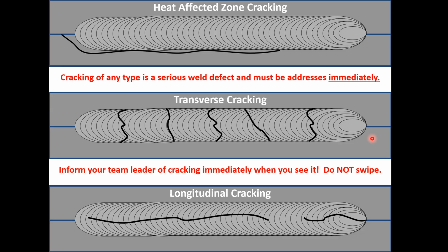Everybody that would call me and tell me we have welds cracking, I don't care what industry you're in, it's a serious, serious thing because it can be metallurgical, it can be structural, it can be contaminations. There's a bunch of different things. So first thing, before I start talking about these, I want you to know that there's no such thing as an acceptable crack. And if you're standing there and you see one, your job is to stop making parts.